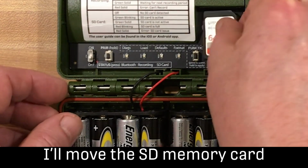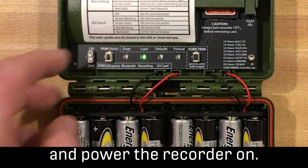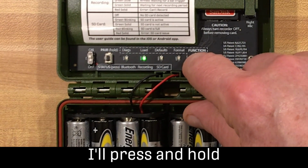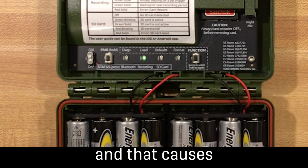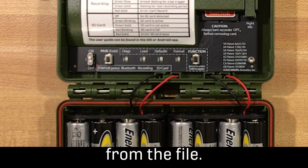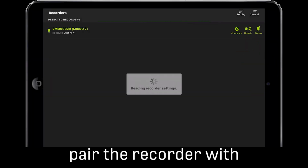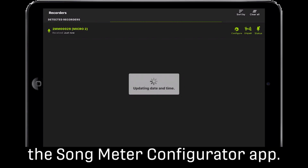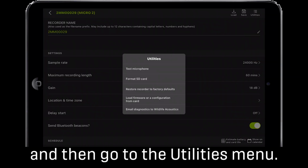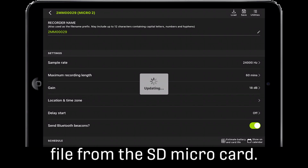I'll move the SD memory card to the Songmeter Mini BAT2 and power the recorder on. I'll tap the function button until the load LED is lit. I'll press and hold the function button, and that causes the Songmeter Mini BAT2 to load the configuration from the file. For the Songmeter Micro and Micro 2 models, pair the recorder with the Songmeter Configurator app. Tap on the Configurator icon and then go to the Utilities menu. Tap the command to load the configuration file from the SD micro card.